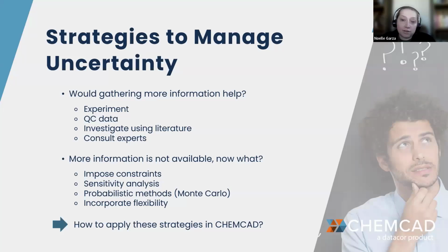And sometimes we do get errors in this data though. So even though you're gathering data, it's important to quality check the data that you have, because there could be errors in it. It could be that the data's a measured value. In one example, crude oil composition gets measured from the well, and they can only measure using GC analysis up to a certain carbon chain length, while very high carbon chains, C50, C80, C200, occur if you have a really heavy oil.